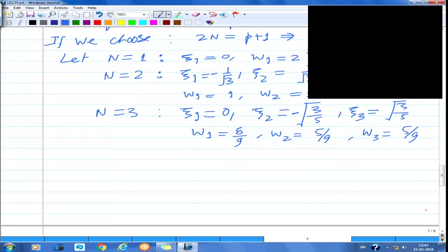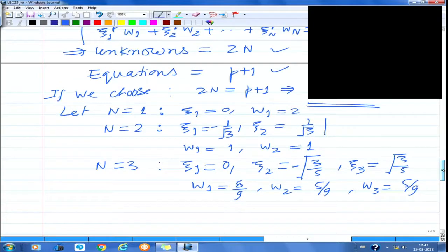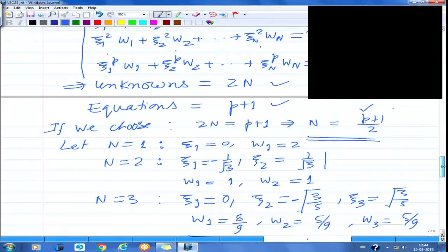So once you have this, now if you look at similarly n equal to 3, you would be able to, now if you want to look at what would be the kind of polynomial you can integrate. So see, 3 into 2 here, 6 minus 1. So basically you can exactly integrate a polynomial which is quintic, that is involving highest power of xi as 5. So this is how you get these gauss points and the corresponding weight factors. Now the integration then is simply the summation.